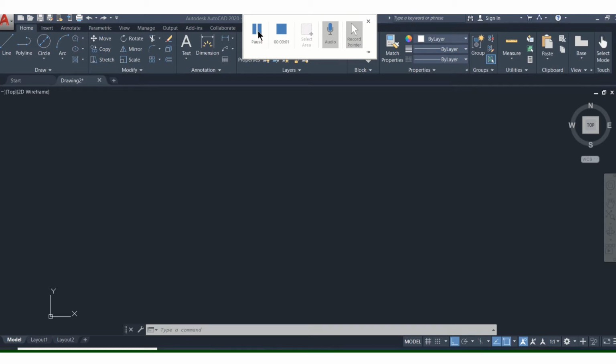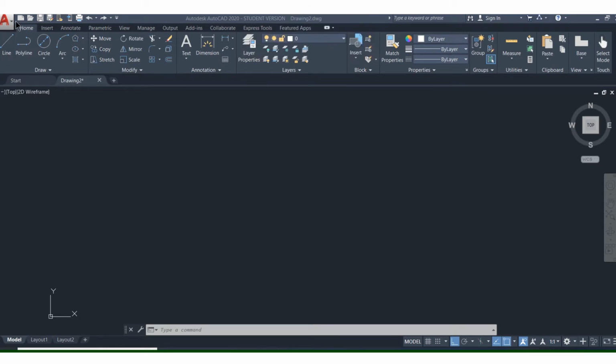This video is going to be a demonstration about how to use the drawing tools in AutoCAD. So up here in our ribbon, we're going to look in Draw, and let's just start with Line. Now remember, check your settings. I've got my ortho on, my object snap on. Line tool is pretty straightforward.